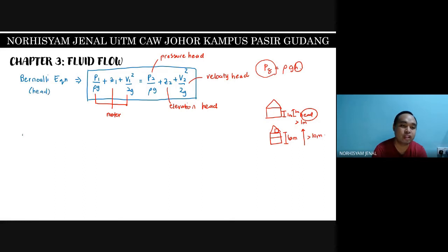If you want to see Bernoulli equation, I simplified by BE over here, in terms of pressure, what you should do is you multiply every single thing over here with rho G. Okay, so what you do is BE in terms of head multiply by rho times G. Okay, so what will happen to this equation over here?